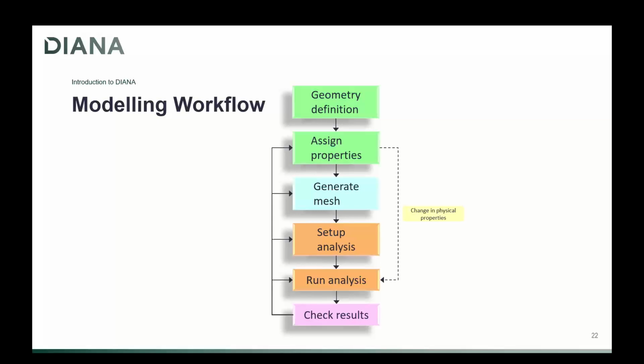So it means that when you want to change something, I don't know, a material parameter, a load or a boundary condition, you do that at the geometry level. So before this change is reflected to your finite element model, so to your mesh, you need to remesh. Just be aware of that. So everything is done at the geometry level. So to transfer that to the finite element model, you need to mesh. So just be aware of this.